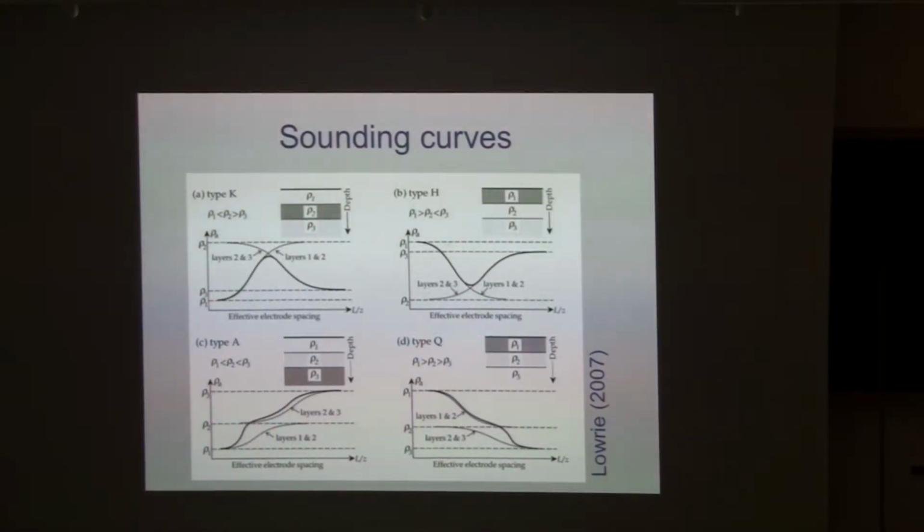By increasing your separation, you're going to get this sounding curve. So you're going to see something not so resistive, more resistive, less resistive in a sort of smoothly varying behavior, because again, our measurement is an average, and we're going to average just over different scales. And to get from here to a model, that's why we do inversion, and I'm not going to talk about it in this lecture.